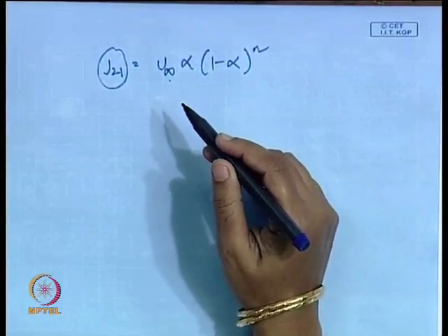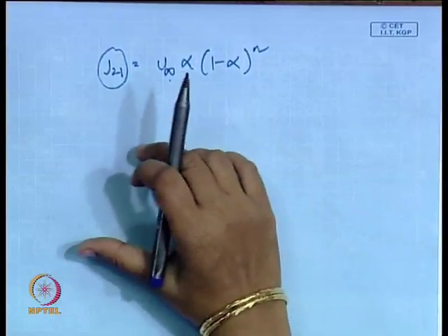I had proposed the different regimes where different values of u infinity and n are applicable, and those regimes were based on some non-dimensional groups. One was definitely the bubble Reynolds number, the others were G1 and G2, two dimensionless groups with liquid properties particularly incorporated in them.